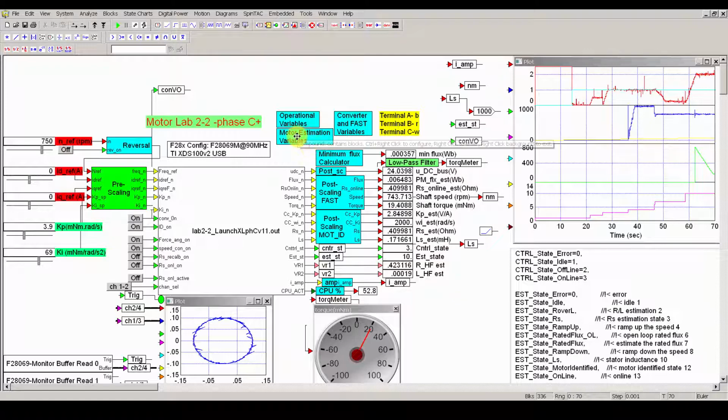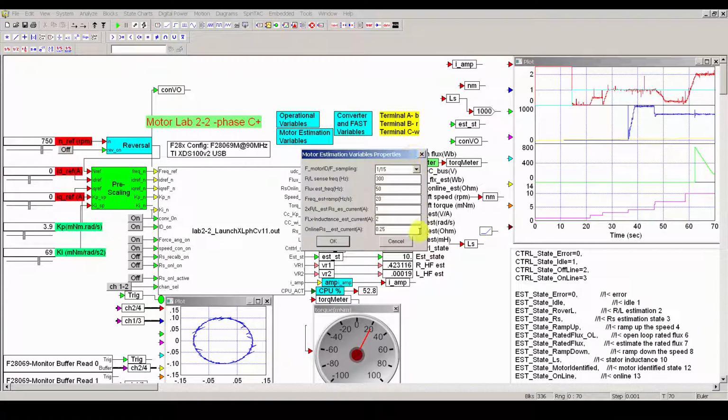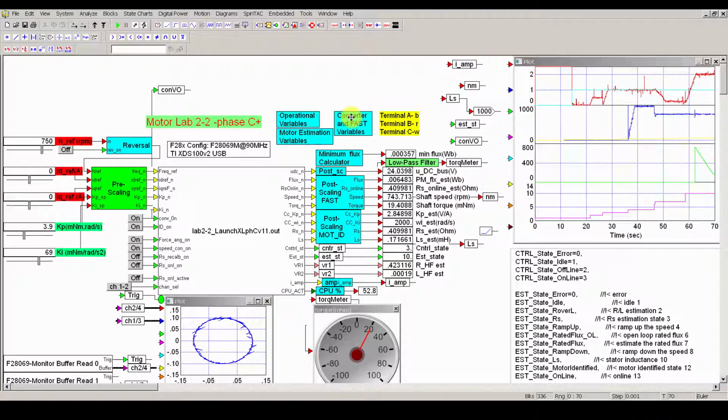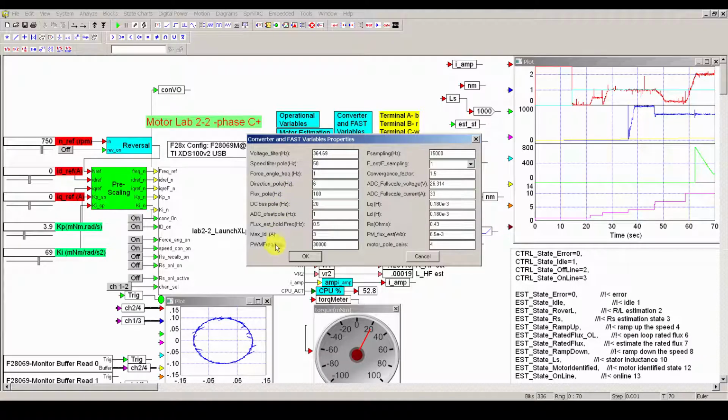And the parameters you need to set are set here. So these are some of the parameters for setting up the identification. The other parameters here are the ones we set up for doing FAST by itself, which we did in a previous presentation. So really, it comes down to encoderless control, any type of machine, PM, non-salient, but also stepping motors is another option. Two-phase machines, single-phase induction machines, any machine can be done in a very short time.